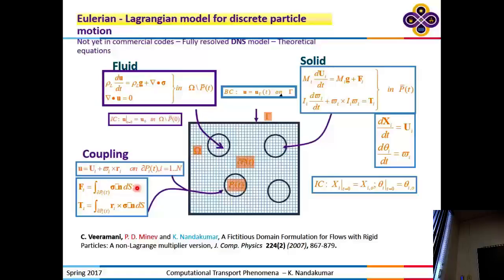So yesterday, in the last lecture, we talked about two-way coupling. Right? When we are doing the Lagrange dynamics for the discrete particle modeling, when the particle concentrations are small, we just put a drag force here, and we don't take the coupling back into the fluid domain. But here, we take that coupling back into this. So if the particle moves or rotates, that imposes the fluid flow velocity in the flow field. So there is truly a two-way coupling.